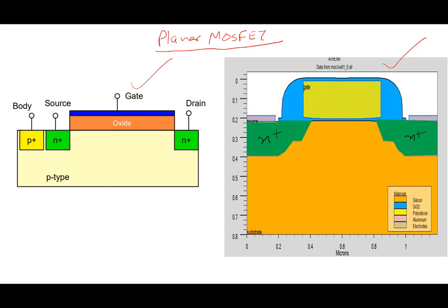The other thing is that there is a spacer layer here. So this is the gate, from here to here, and then there is a spacer layer. We'll not go into it. These are needed for fabrication from a processing point of view. It's an insulator, so we call it a spacer layer. It's an insulator only, silicon dioxide in simple cases.